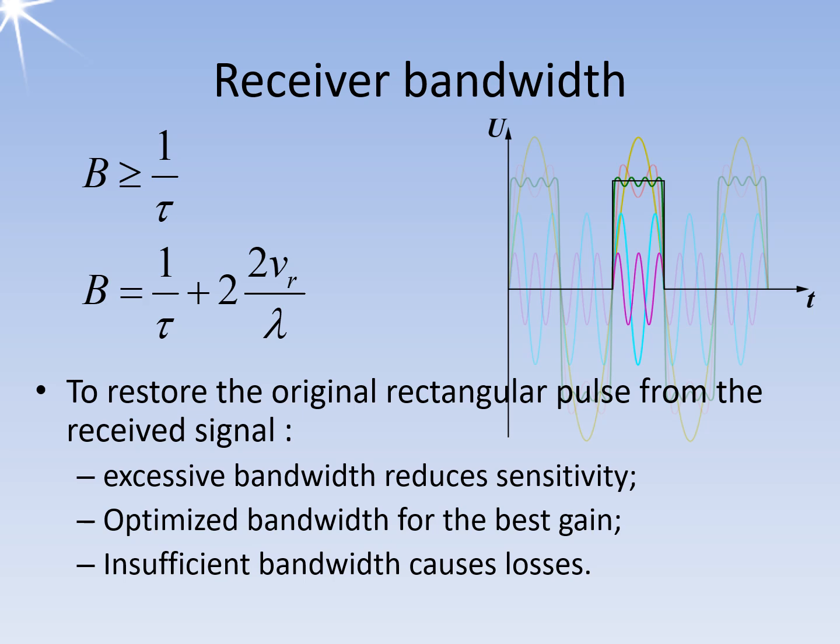In practical applications, however, the carrier frequency of the radar is affected by Doppler shifts. This needs to be considered when determining the bandwidth. The Doppler frequency must be added to both sides of the bandwidth for targets that are either approaching or departing. For instance, at a radial speed of 1000 meters per second and a carrier frequency of 11 centimeters wavelength, the Doppler frequency shifts to plus or minus 18 kHz.